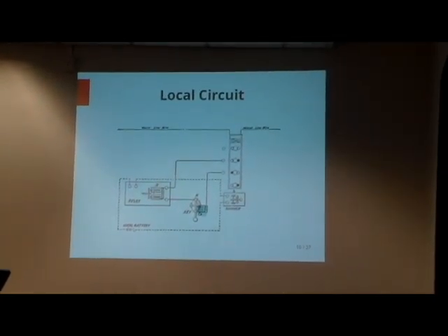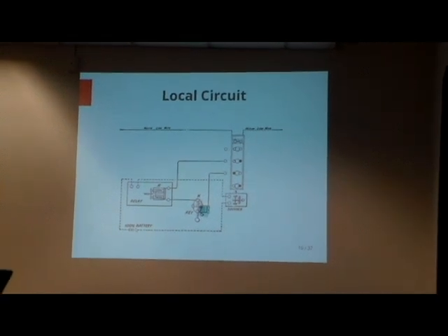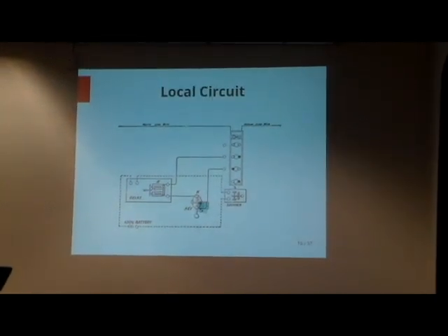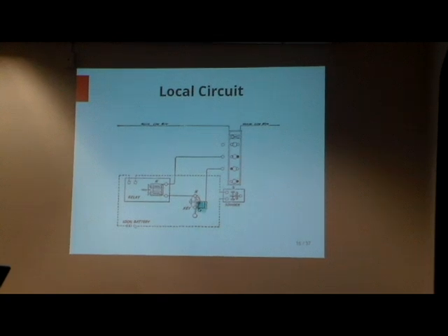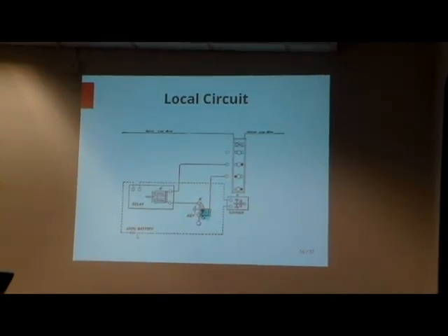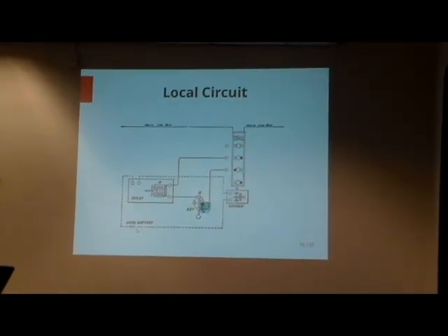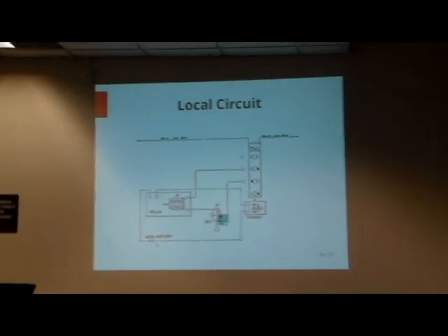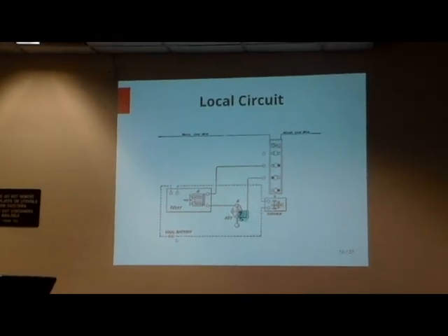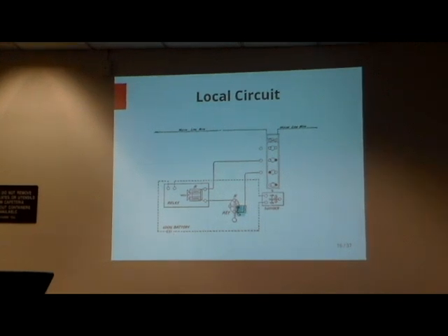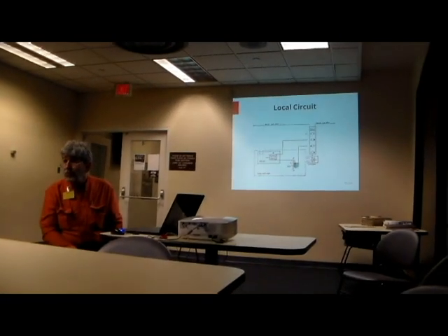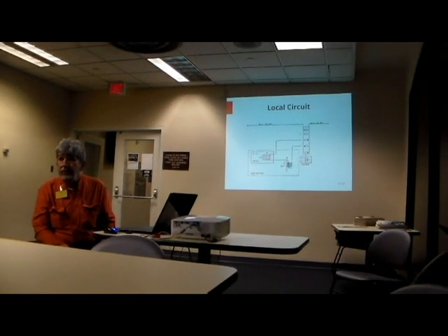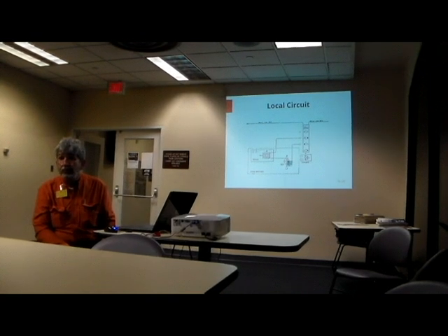Because when you had a shack beside a railroad that was a signal station, or a tower beside a railroad, there wasn't necessarily any electrical service available to that location. And it was not in the railroad's interest to build power generation there. But if all you have to power is a 4-ohm sounder, divide your amp by 4, and you've got the quarter of an amp it takes to run the sounder. It runs on 250 milliamps, a local sounder at 4 ohms.